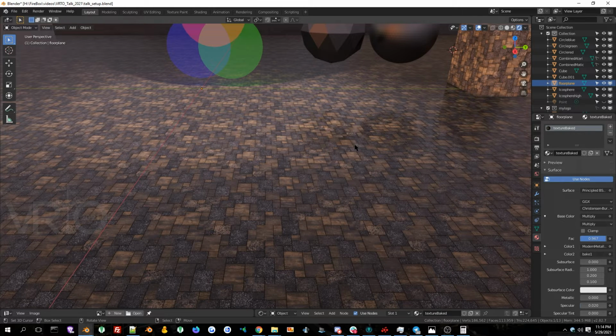Use tiling textures as much as you can, and if you must, use ZBrush, which I would recommend for stuff like character models, or Substance Painter, single UV maps. I would only use those, but I would avoid using them if you possibly can. Don't paint an entire environmental scene or an entire building with ZBrush, or otherwise you're going to have huge textures or really, really bad resolution. Same thing goes with photogrammetry. Try to optimize it as much as you possibly can.